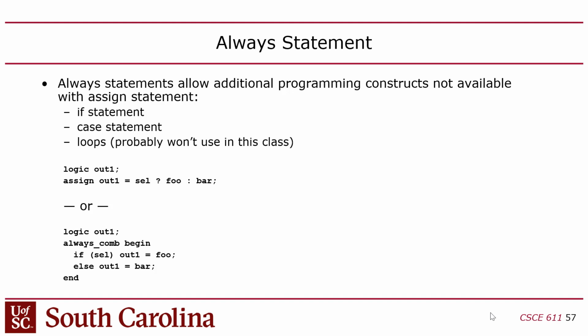Now in this case, what are the inputs? Well, select is treated as an input, and foo and bar are inputs here, right? So I basically have 3 inputs. If any of these 3 inputs changes state, that will cause an event to trigger, which will update out1 immediately, I mean, just after the logic delay. The way that out1 is updated behaves as though I'd run this sequentially, but it's still not sequential.